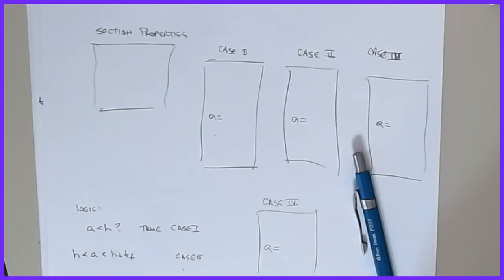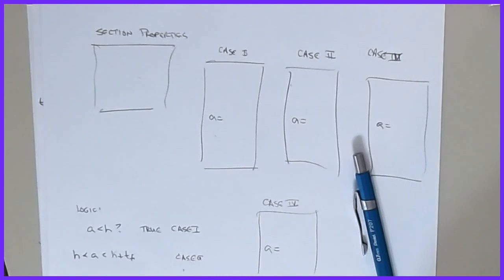And then I went through and did the same thing on the next one. And what happens in all of these is that the A that I calculated on this, we found out it was 1.64 inches. And if you go back and look over here, I said my slab thickness was 5 inches. So I knew that it was in this one. That's why it went highlighted green. If I change this to like a 1, with some conditional formatting, it went over and figured out where that A had to be to make the calculations work.